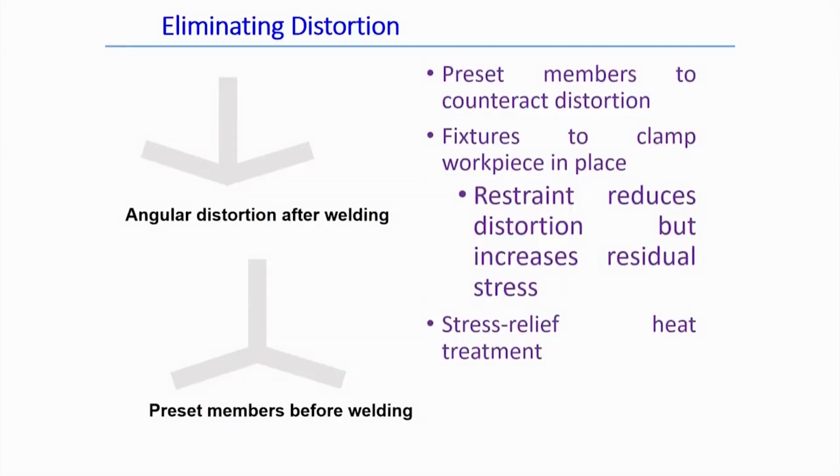But how can we predict these things? That is a serious problem in the welding process, to eliminate the distortion. During the welding process and after finishing it, there is considerable phase transformation and microstructural change, and that happens under some mechanical constraints. All of this is responsible for producing some amount of distortion and residual stress in the final weld joint.